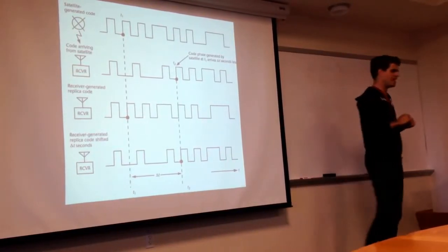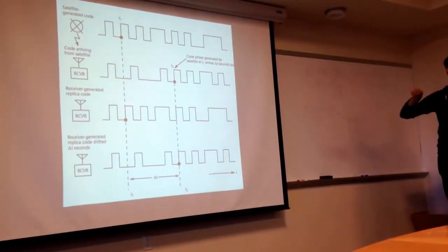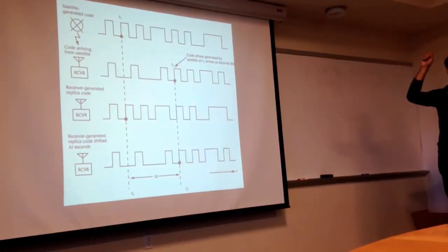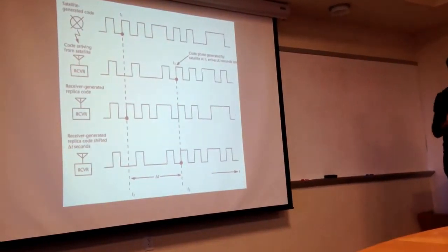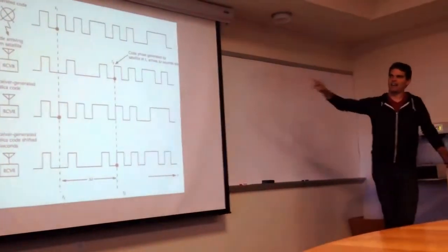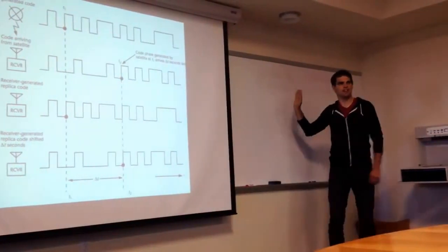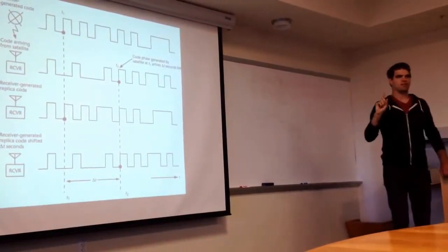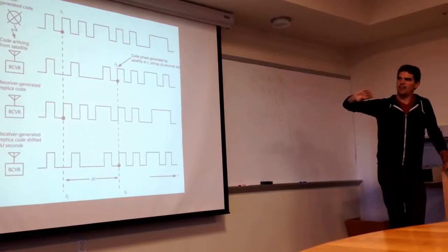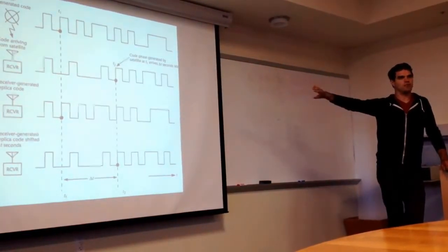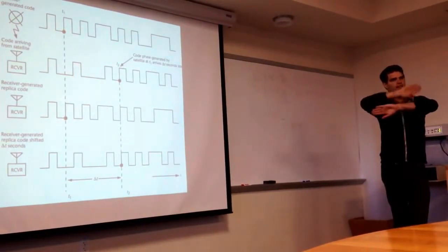If it so happens that I've got noise in my signal, then that translates to the fact that some of these bits are going to be corrupted. They will be sent as a 1, but I'll receive them as a 0 or as a half or what have you. It's just analog noise on this. That's okay, because I have 1023 of these bits, 20 repetitions of that, just to send a single digital bit, which means that I have a huge amount of noise resistance, because I can corrupt many of these small bits, and that's okay, as long as for the most part it comes out that I do line up.